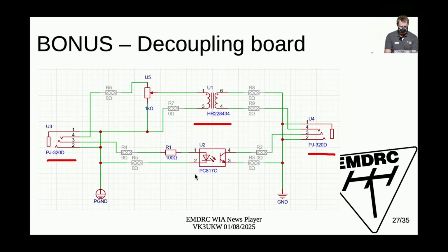And then at the bottom, we've got an optocoupler. What happens in an optocoupler is that instead of having an electrical connection between the two sides of your signal, you interrupt it in the middle and use light to transmit your information. Inside there, you've got an infrared LED, and over here you've got a diode, and all diodes are photosensitive.